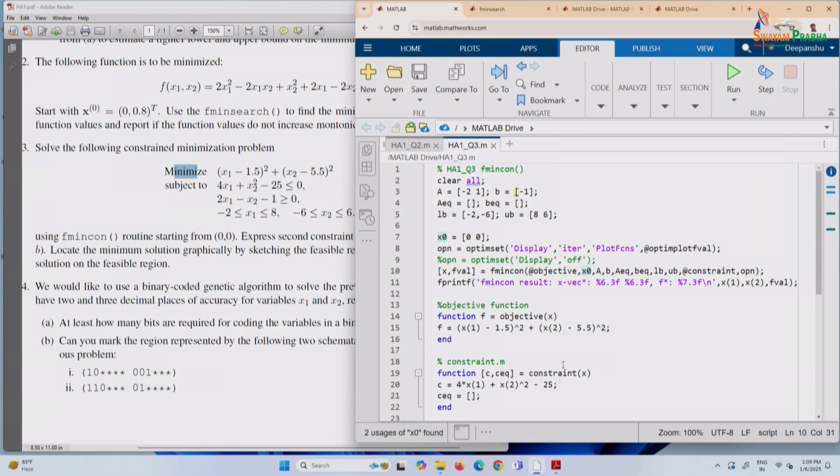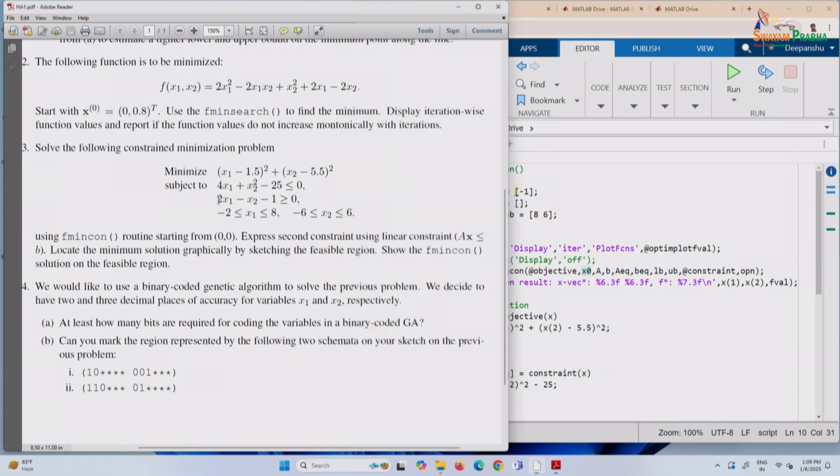Chrome. So look at this constraint. This is a linear constraint, so I can use Ax less than or equal to b. If I convert it into A times x less than or equal to b, what is my A matrix? The coefficient of x1 is 2 but it's greater than. I probably didn't tell you: when it's greater than, you want to convert it into less than, because fmincon wants you to use less than or equal to, right? So we can multiply both sides by -1, and then the sign will change to less than or equal to.